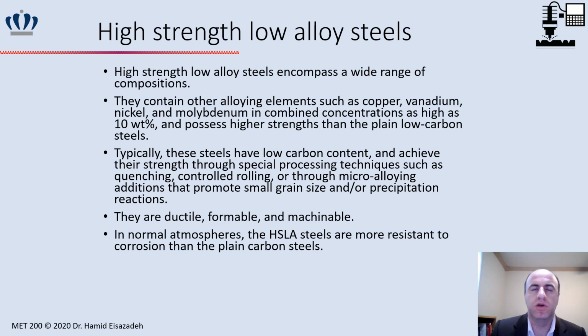Another group of low carbon steel is called high strength low alloy steel, or HSLA steel, and this is very popular steel. They contain alloy elements such as copper, vanadium, nickel, molybdenum, and the combination of these elements can be up to 10 weight%.